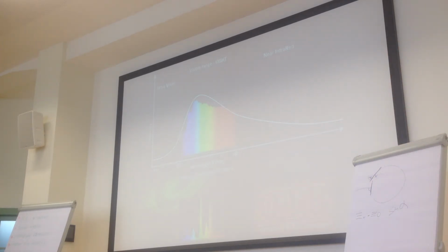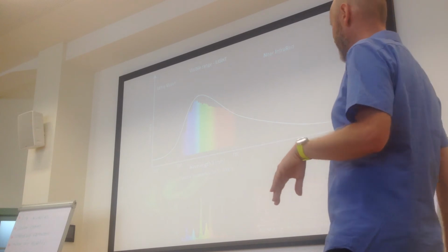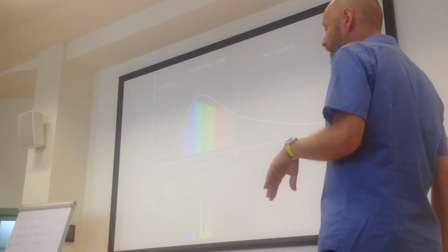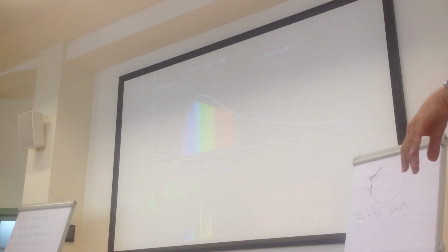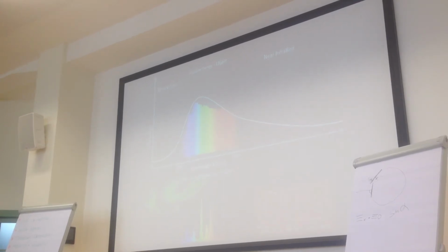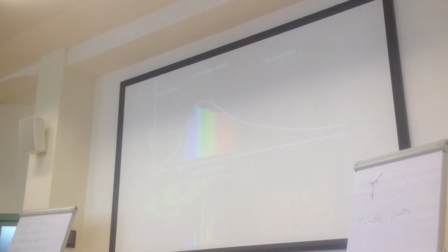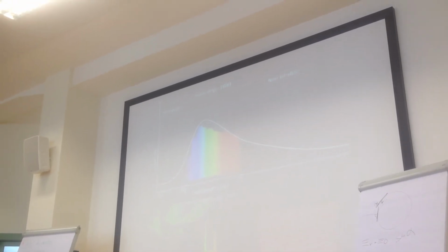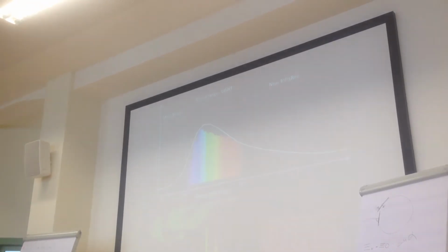This is really a very, very simple and useful tool, and it might give you good information about the quality of lighting systems. So when you have to select some lamp types for your project, and you have this spectroscope with you, you can get a very good impression about the quality of the light emitted by those lamps. And it's really very cheap, and it is really very useful.